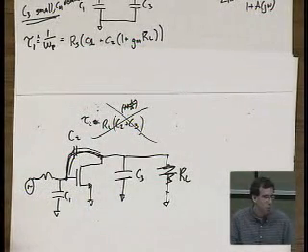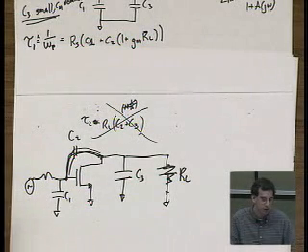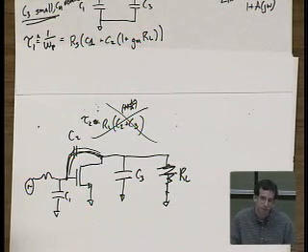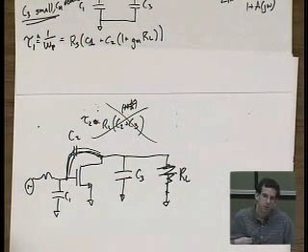Okay? I just made a weird logical leap, and I see a lot of confused expressions. Are there any questions as to the logical leap I just made? Yeah? I thought when you Millerize it, you put C2 to the ground on the other side, like C2 parallel with C3. Mm-hmm. Right? Because the Miller effect is not a lot. It's like 1 plus 1 over A.